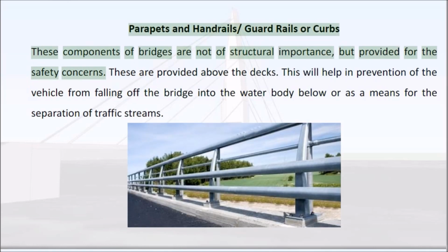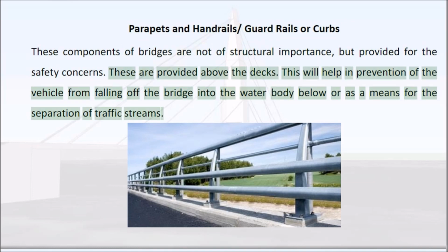Parapets and handrails, guardrails or curbs. These components of bridges are not of structural importance, but are provided for safety concerns. These are provided above the decks. This will help in prevention of vehicles from falling off the bridge into the water body below, or serve as a means for the separation of traffic streams.